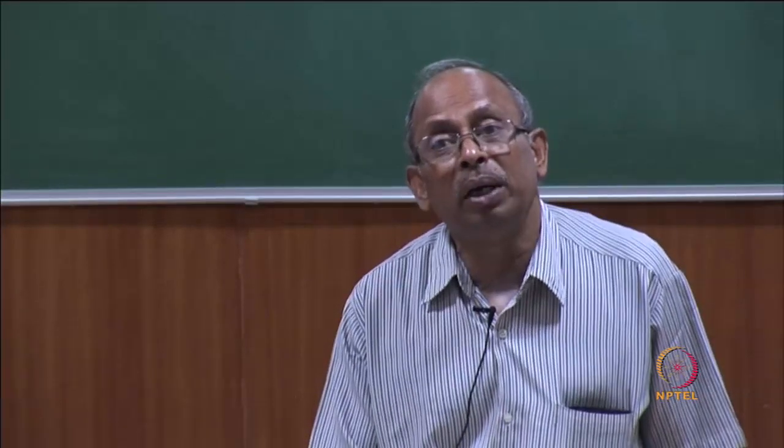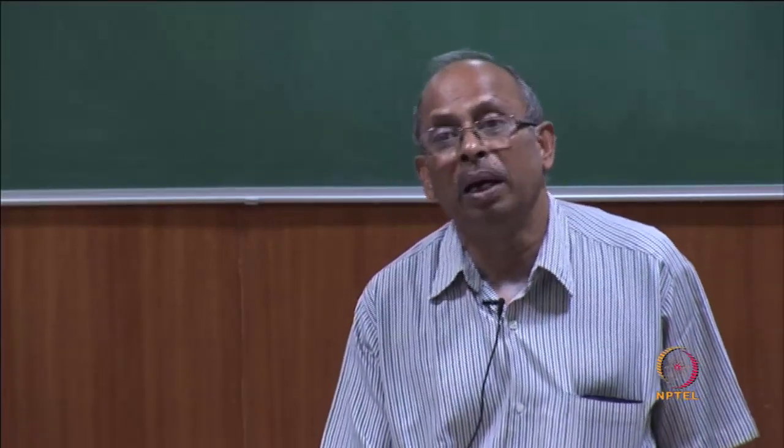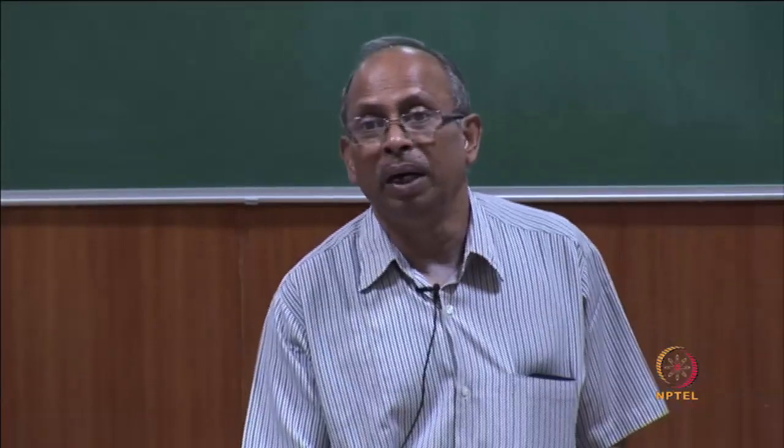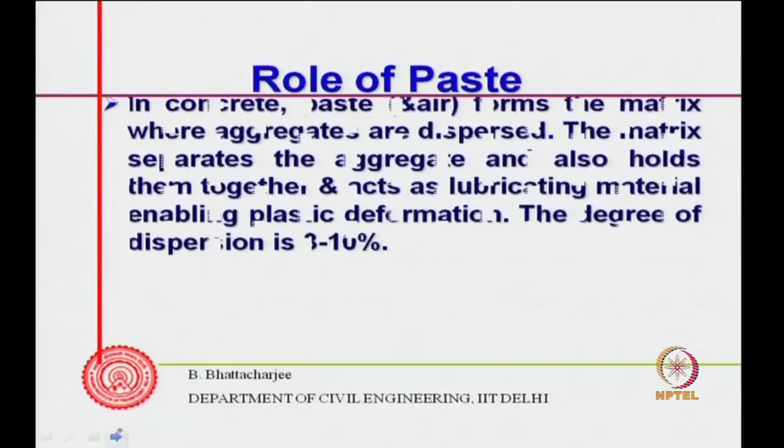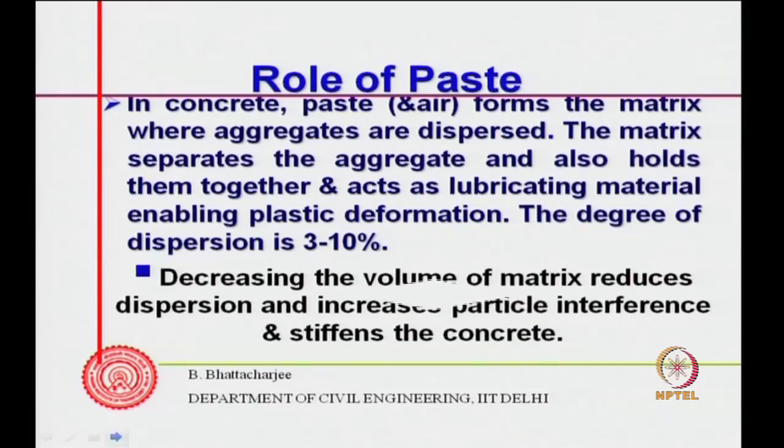In case of concrete, it will be the water content vis-a-vis the total mass or volume of the aggregate and concrete system. So, water content is what would govern this viscosity. So, in concrete, paste forms a matrix where aggregates are dispersed. The matrix separates the aggregate and also holds them together and acts as a lubricating material, enabling plastic deformation. The degree of dispersion is 3 to 10%, that is what we said. So, therefore, decreasing the volume of matrix reduces dispersion and increases particle interference and stiffens the concrete. So, role of paste is very important.